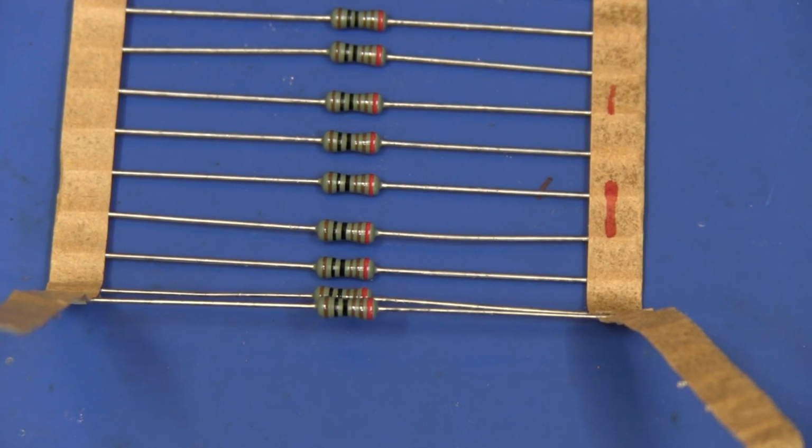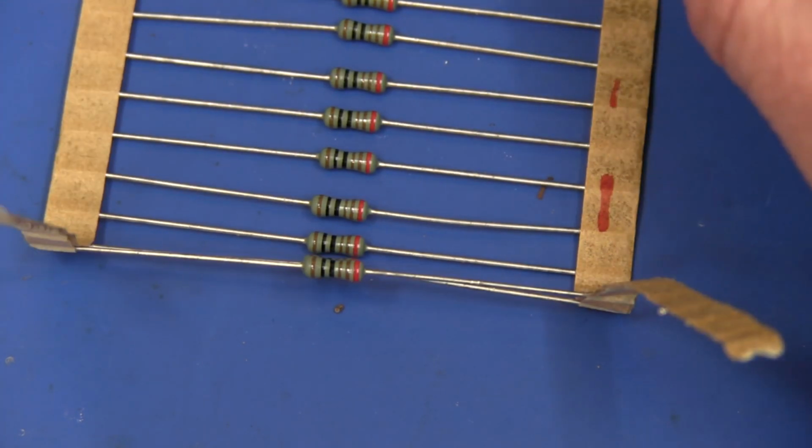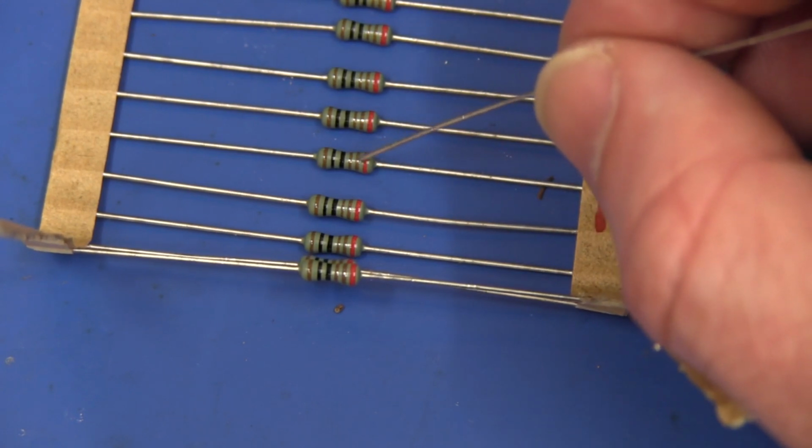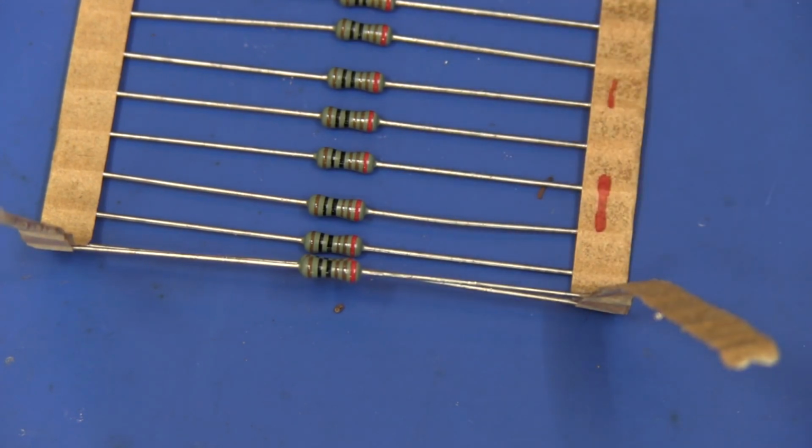Now, of course, if this was a regular 3-band resistor, a 5% tolerance one or whatever, if it only had 3 bands, then for 1K it would be brown, black, red. And if it was a 4-band resistor, it would have brown, black, black, brown. Now, the 5th band indicates the tolerance. In this case, it is brown, and that indicates plus minus 1%. If it was red, it'd be plus minus 2%. If it was green, plus minus 0.5%. Blue, 0.25%. Violet or purple would be 0.1%. And if it was grey, it can go down to 0.05%.